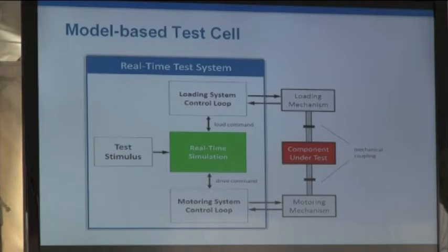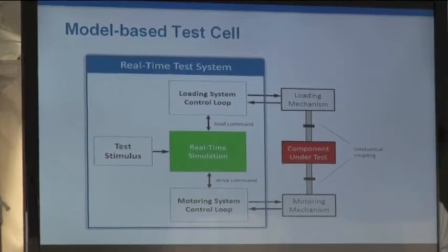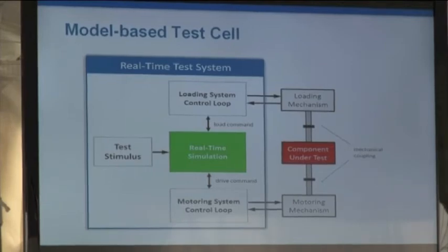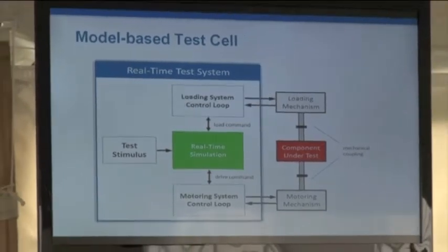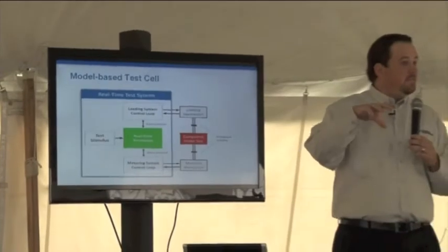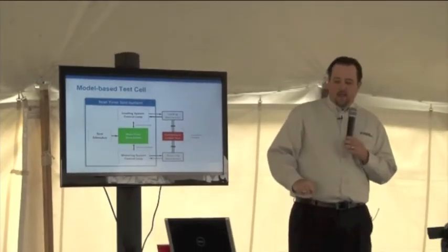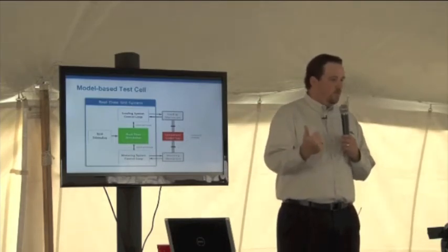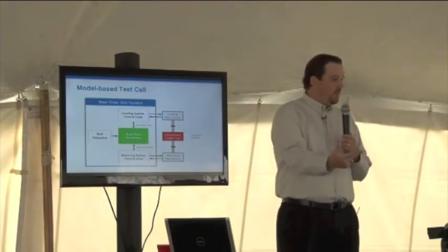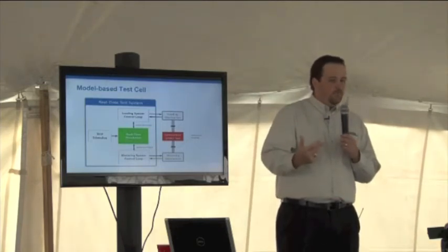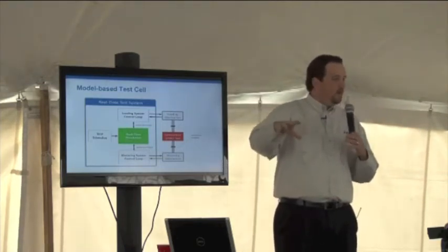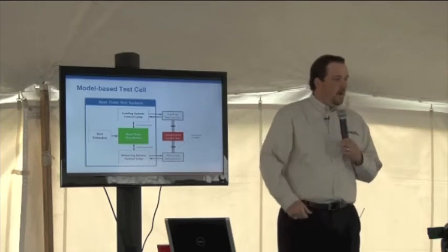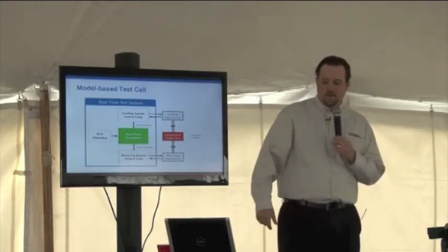And the way that what's happening there is actually the model itself, this model of the entire system. Here, let me dial in to make this a little easier. So let's say we have a powertrain system, okay, but we want to test just one piece of that, maybe the differential. Okay, the way the model can be used then to test that differential physically in a particular vehicle configuration is to take a model that takes into account, well, what kind of transmission do we have, and what is the motor that we have, what kind of drive cycle is going to be done there, and how's the driver going to respond to that, and what are the tires, what is the friction with the road, and the actual dynamics, the inertia of the vehicle.